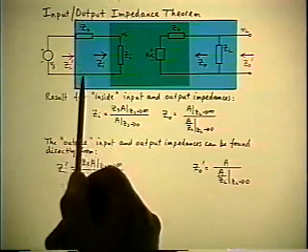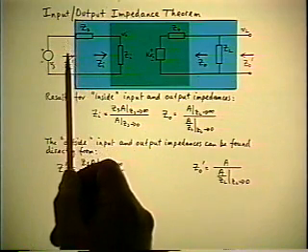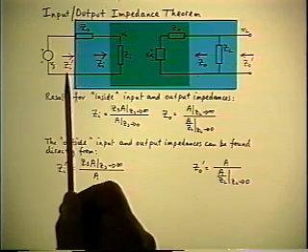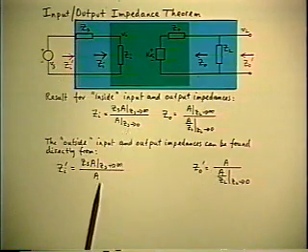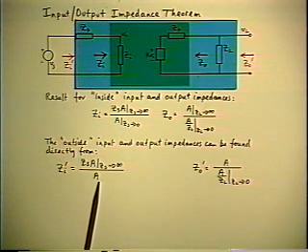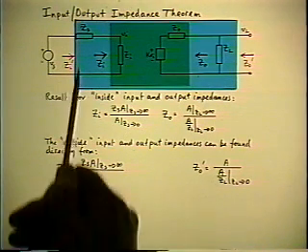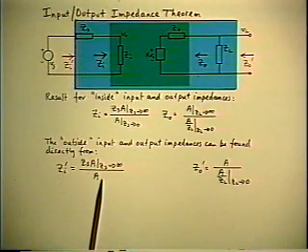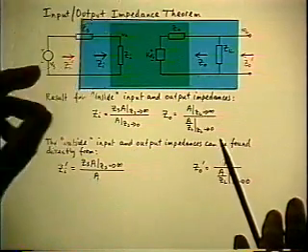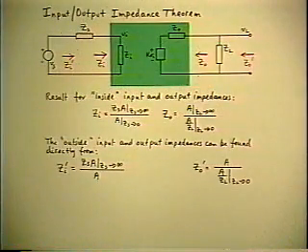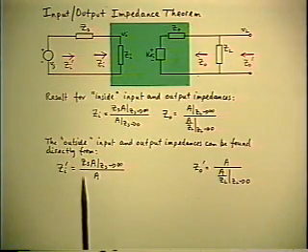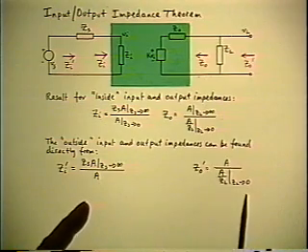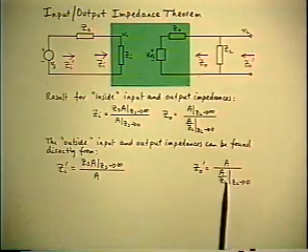The only difference is the input voltage of the blue box already has no external source impedance, so you don't let ZS go to zero in the corresponding term. The external source is already zero for the blue box. So by using that intermediary of the fictitious blue box, I've established that these are the right formulas for the outside impedances of the green box.